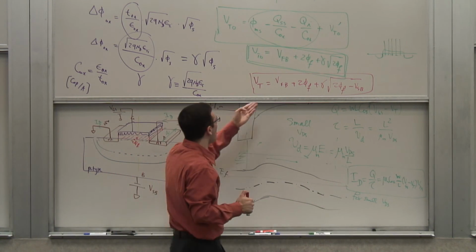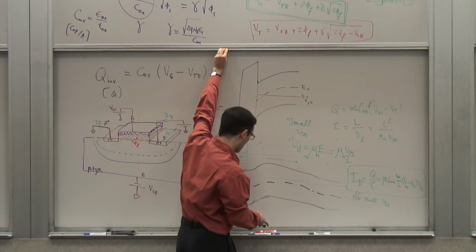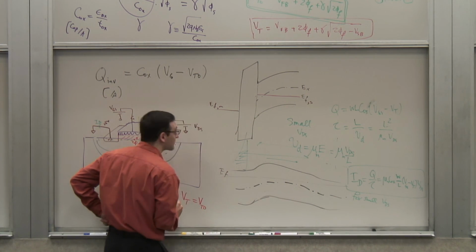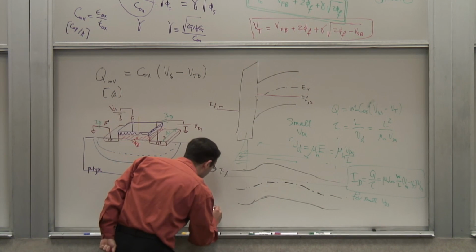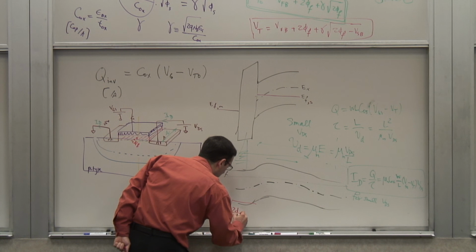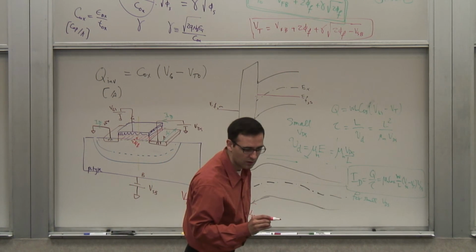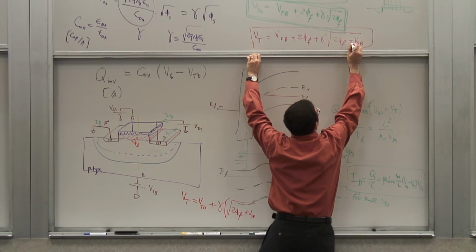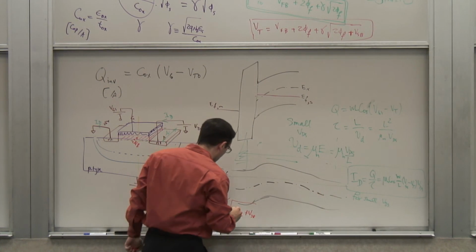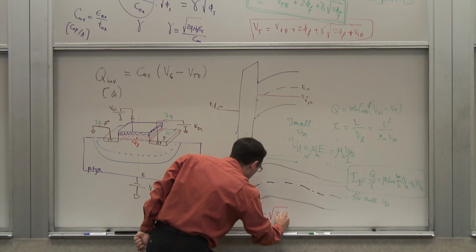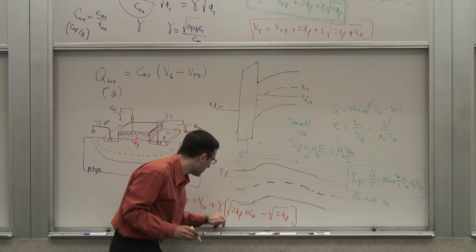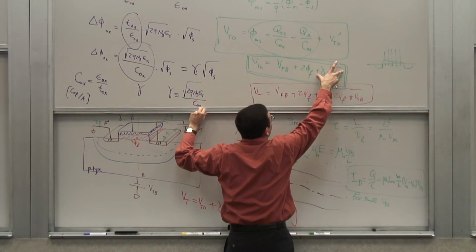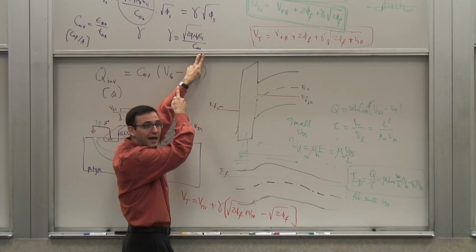And, well, we usually don't want to deal with all of these terms when designing circuits, so we rewrite that in a slightly different way. We say VT is VT0, the original VT0 that we have, plus gamma times the square root of 2Vf plus VSB, because of the polarity, minus the square root of 2Vf. Remember, there's a gamma square root of 2Vf in the VT0, right? So this term cancels that, and what is left is this term. So this is exactly equivalent to that.